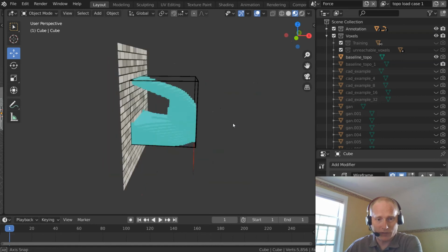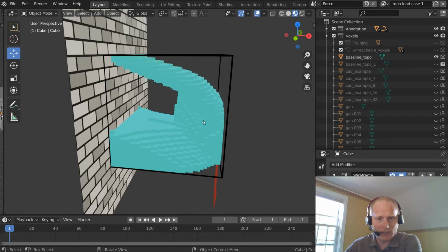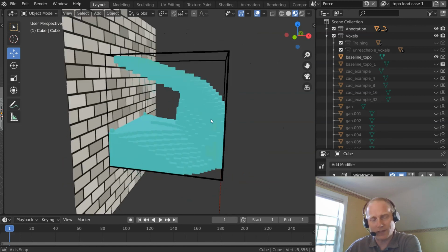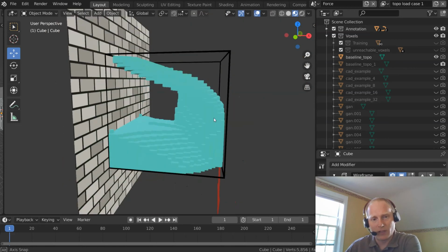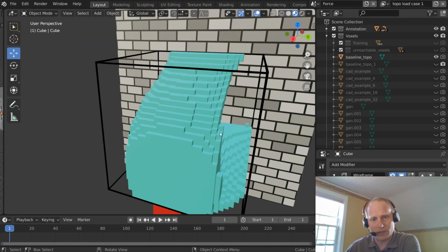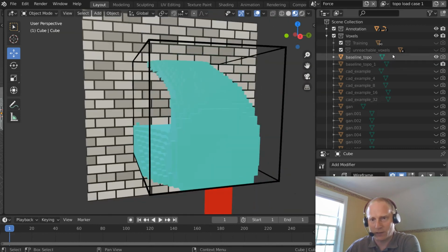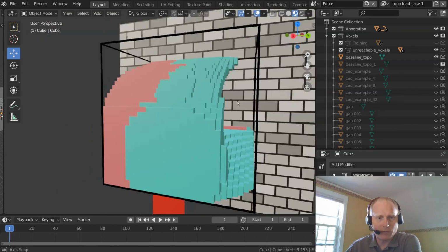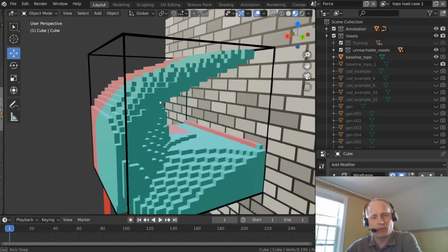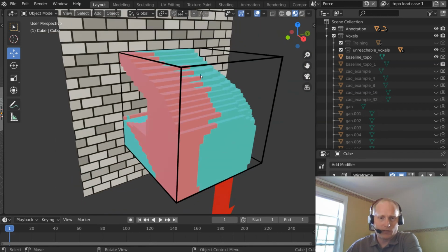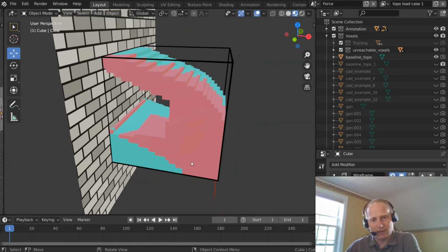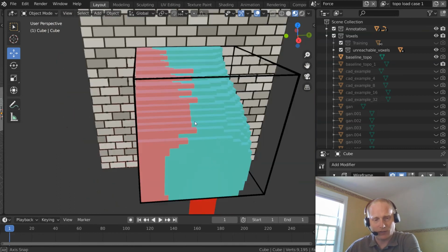So here we can see the traditional topology optimization, and you can see that this design could not be manufactured with a one setup on a 3-axis CNC machine. You can machine it from this direction, but you're not going to be able to get some of the material removed here. And I'll illustrate that a little easier. I'll just show you the voxels you can't reach. These red voxels would be what should be removed, but can't be removed by a one setup 3-axis machining. And what I did was look from each of the 6 sides, find the direction that had the least unreachable voxels, and that's shown here.